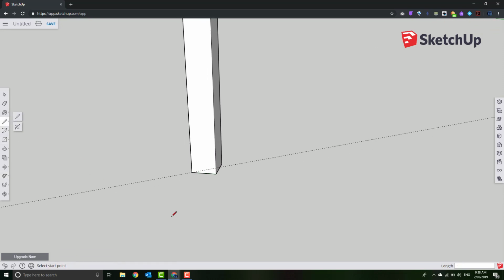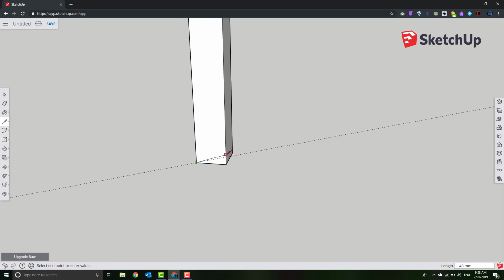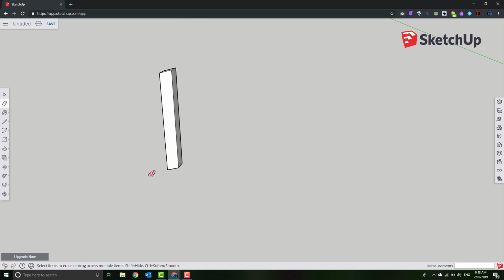Take my pencil, corner to intersection, push pull through that edge. Now I can just go up here and say that's the edge I want to go to, everything's perpendicular and straight, and I would then delete that line. Don't need it anymore. I want to straighten it.